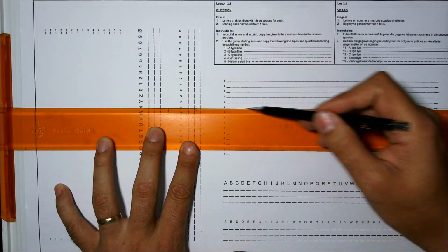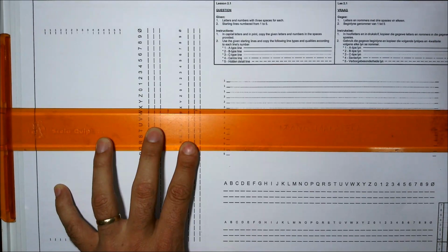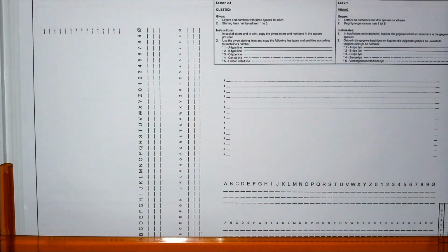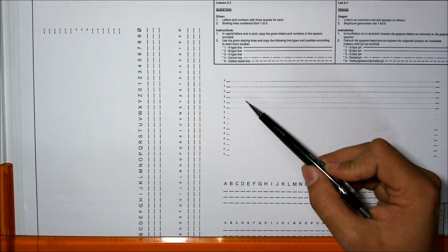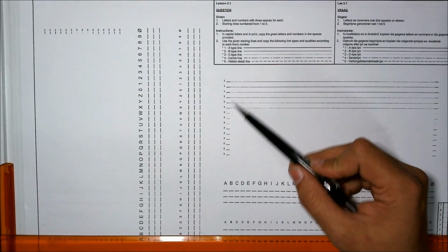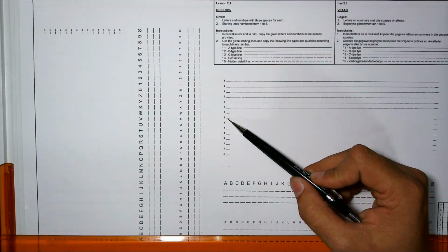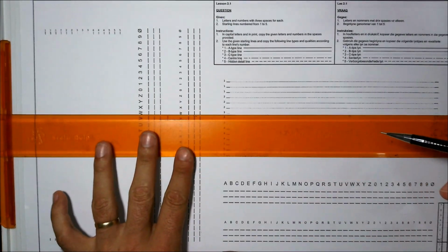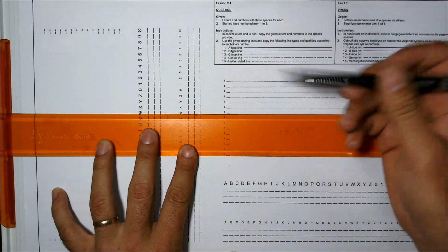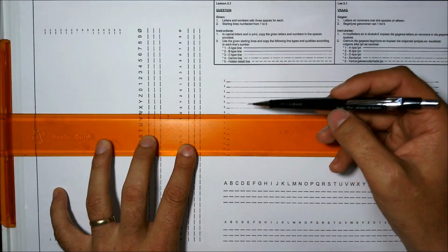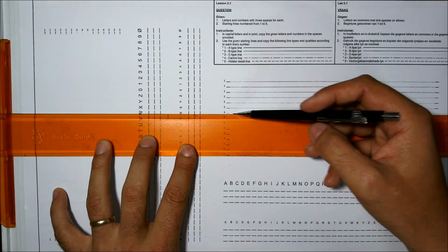I really want you to take your time when you do this. Don't think it's just a line you have to draw quickly. These first three have to be dark lines. Then number 2 is B lines, which is a medium line type. And then we have 3. The third one is a construction line. This is where you typically just put your pencil down and let it glide.